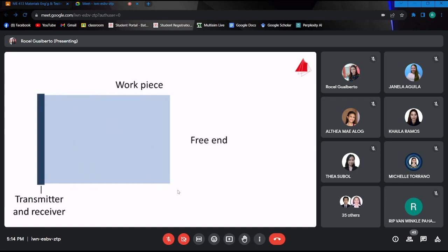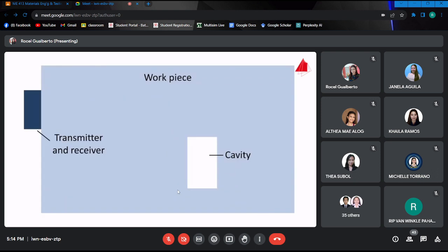For ultrasonic testing of a workpiece, not a large transmitter is used in most cases, but a rather compact one, which generates a short ultrasonic pulse. At a place free from defects, the ultrasonic pulse travels to the right front end, also termed backwall. The pulse is reflected and recorded again as an echo.